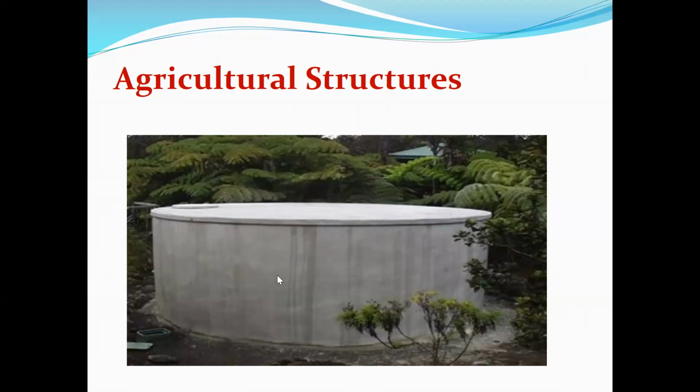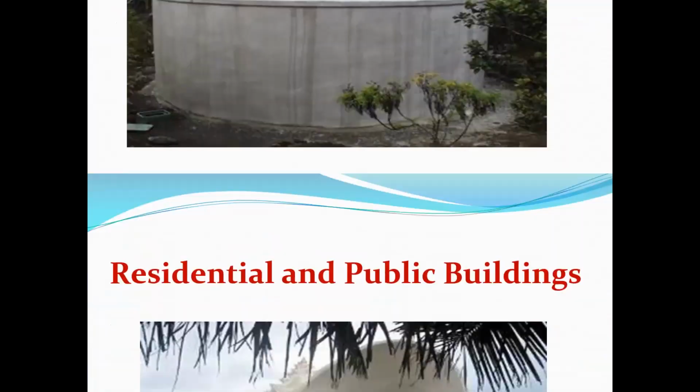When cracks develop, since the ferrocement structures are made of very closely spaced reinforcement bars, the crack widths are very, what should I say, thin. Now in conventional concrete, if a crack develops, it becomes large. But in ferrocement structure, since the reinforcement is closely spaced, if cracks develop they will be numerous, but the crack width will be small. That is why it is preferred as a water retaining structure. When used at low scale or in improvised conditions, in remote areas, ferrocement structure is a good solution.